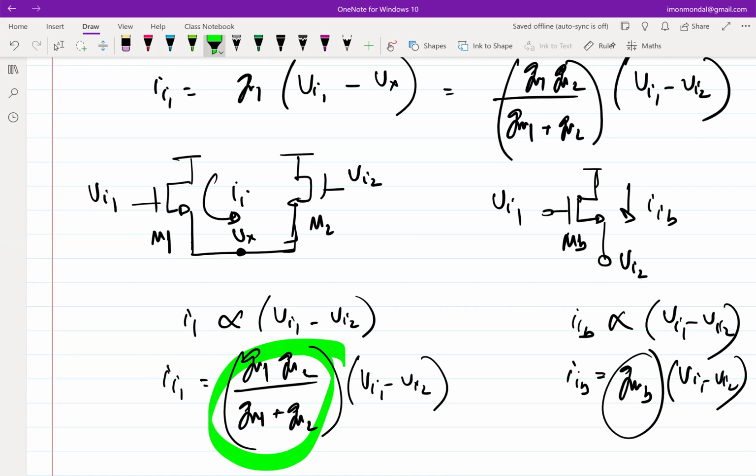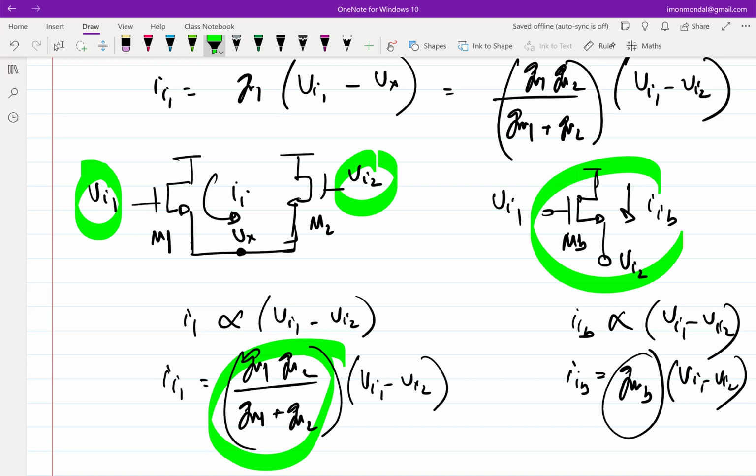Right? So one might argue that all the things that we see in a common source amplifier, we should also be able to see in this contraption. But the key difference is that in the common source amplifier, the input is not being loaded when you attach it to the gates of M1 and M2. However, in this case, VI1 has the benefit of not having any current drawn from it, but VI2 does not. If VI2 is sensitive to current being drawn from its source, obviously, if you have an ideal voltage source, there is no problem. But you will not always have ideal voltage sources, so there will be a series resistance with VI2. So you will not get the benefit of the often high input impedance. However, in the second case, you get it. Okay, so that is the key difference. Otherwise, more or less, it's kind of similar.